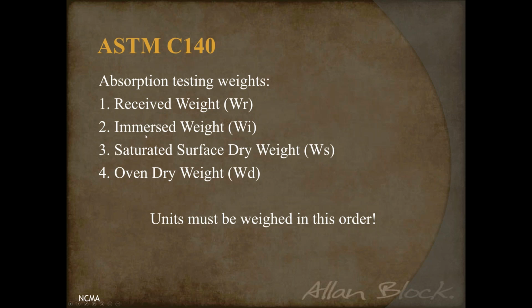You immerse it for 24 hours to make sure it's completely saturated, and you weigh it there. You pull it out of the tank and you dry it off just a little bit, and you take that saturated surface dry weight, and then you oven dry it for a full 24 hours.